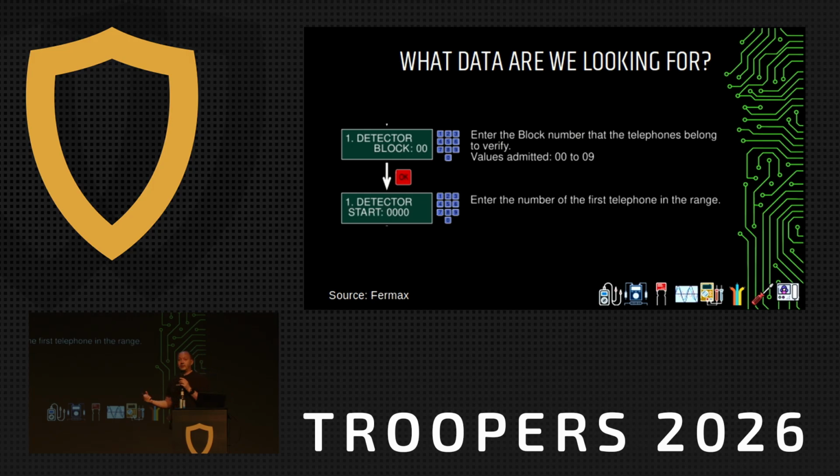Well, from the video before, we saw that the apartment number was programmed, and it was 6 digits. And I found documentation that gives you a breakdown. So you have the block number, which is 00 to 09, which for the installation I had is most likely either 00 or 01, so just the first block. And then the apartment number, right? So 4 digits. Let's say your apartment is number 12, so it's 0012. So I would be looking for a bunch of zeros and then 12 in the end. So you try to look at that and understand what's going on there. Unfortunately, in the tens of dumps that I did, I couldn't find that data specifically and reliably.